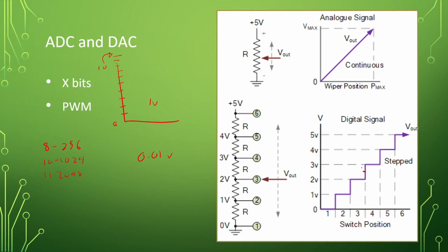All right. This is also why when it comes to analog, you have to be very careful about writing your logic, because you can be like, when it equals 83.4 degrees Fahrenheit, and based on your temperature sensor and your accuracy and everything, it will never read 83.4. It'll read greater than 83.4 or less than 83.4, but it will never be exactly 83.4. So you have to be very careful about your logic to make sure you're doing greater than or equal to or less than or equal to types of things instead of specifically equal to, because that will bite you in the butt. So yeah, the number of steps is going to be very, very important.